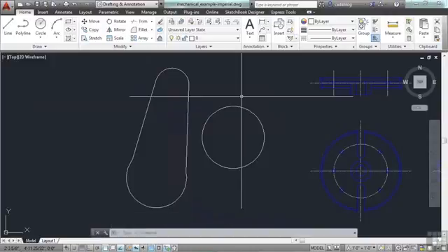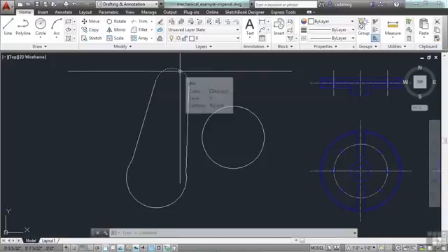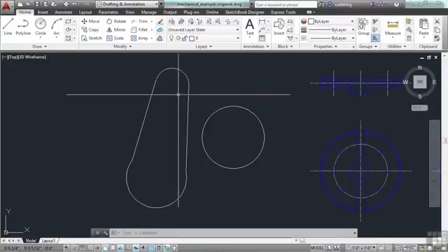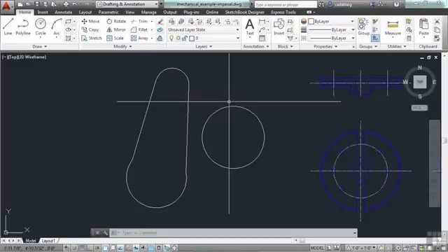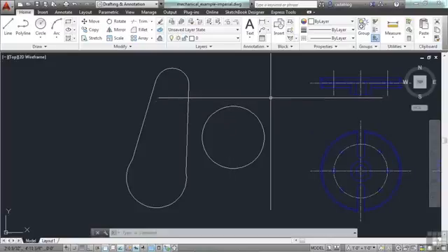So there are a lot of different reasons why you would want to draw a circle in different ways. It's going to be based on the information you already have and with what you want to do. Now, if we knew what the radius of this circle was going to be, or if we knew where the center point is, then it would be very easy to use the default circle commands. So look at your command line when you start a command and see what it says. It will typically show you that you have more options available, but not always.